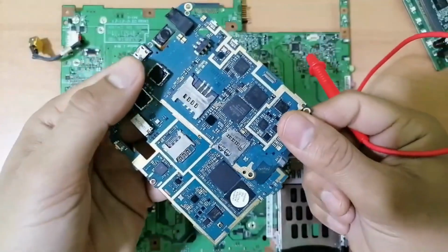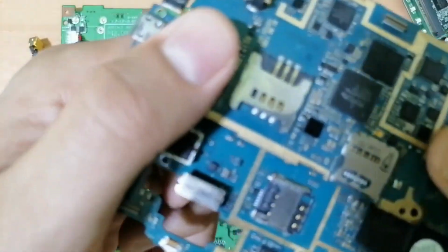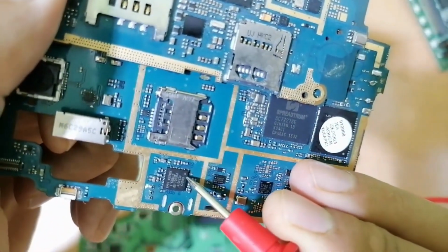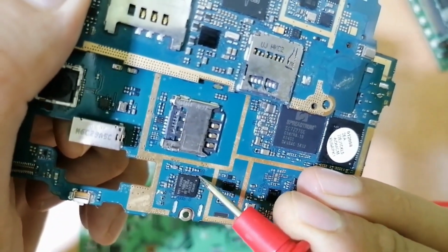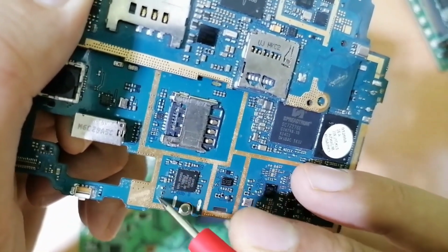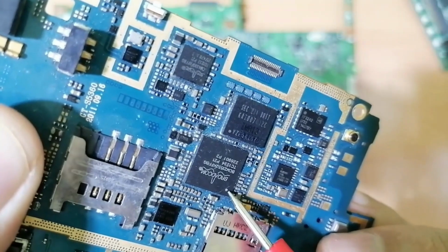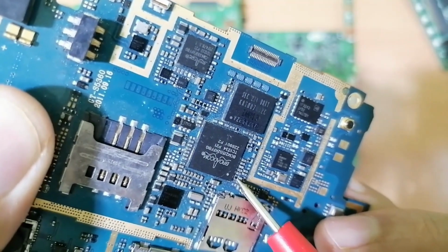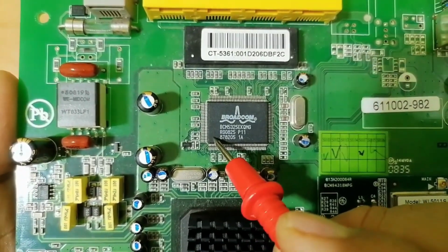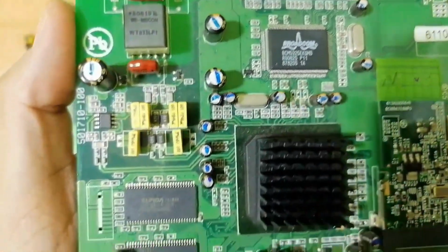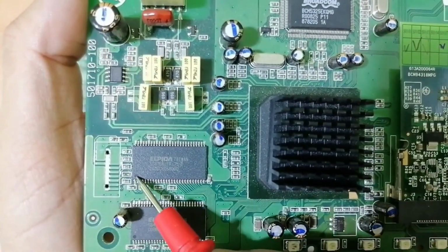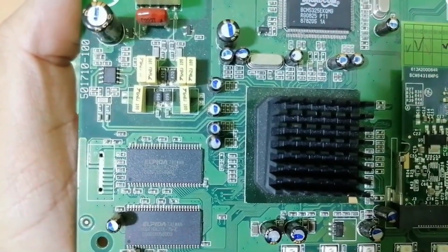So for the cell phone motherboard, as you can see, we have the same working principle. Let's see, for example, this IC. As you can see, we have the dot over here. You see this dot means this is the pin number 1. And as I told you, we always have certain capacitors around the IC. Here also we have the dot over here, which means over here we have pin number 1. So for the router motherboard, we also have a dot over here. Do you see this dot? It means this is the pin number 1. And if we go here to these chips, this is basically the RAM, we have a dot over here and a dot over here, which means this is the pin number 1.